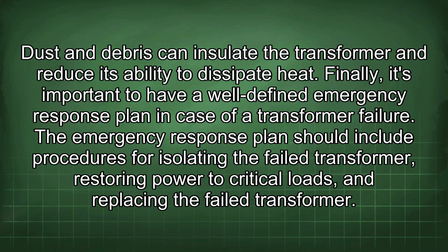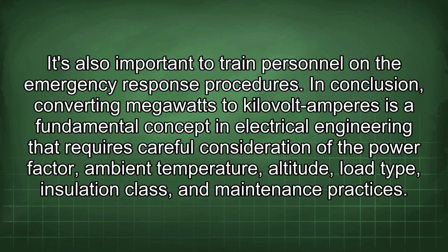Finally, it's important to have a well-defined emergency response plan in case of a transformer failure. The emergency response plan should include procedures for isolating the failed transformer, restoring power to critical loads, and replacing the failed transformer. It's also important to train personnel on the emergency response procedures.